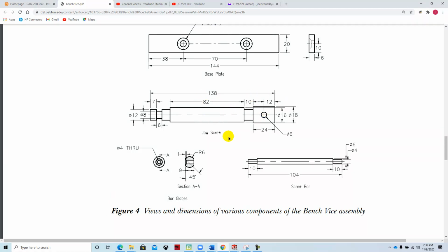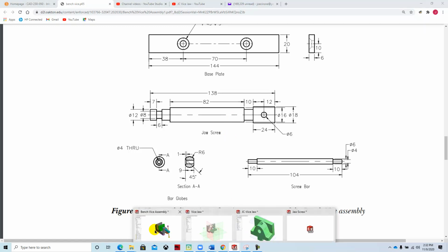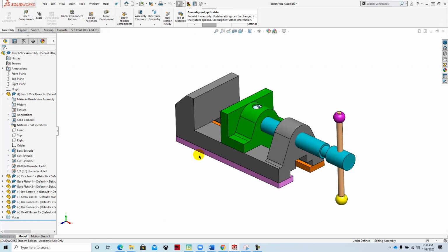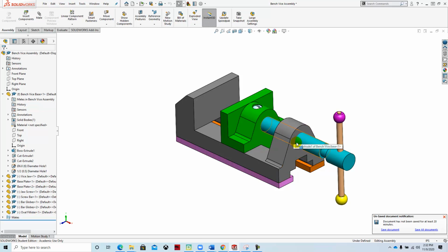If we look at how this part would function, we can take a look at our assembly drawing. If we were to thread this, we can go back to our vise jaw and also thread this hole here. Then when we 3D print it, we can add a mechanical mate, and it will actually simulate the thread representation. You'll be able to actually unscrew it and screw it together.